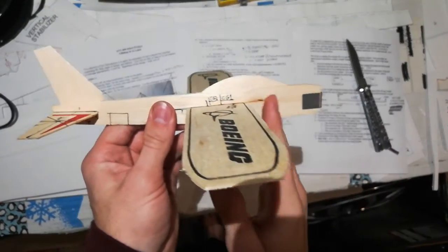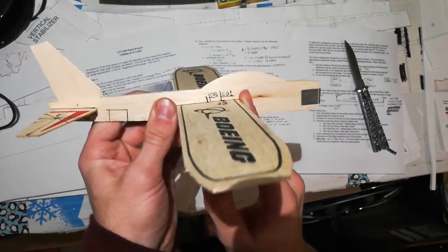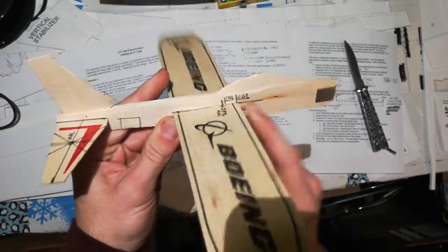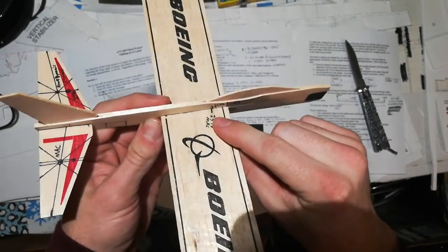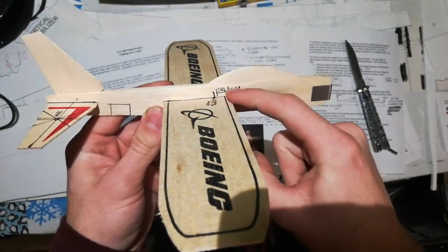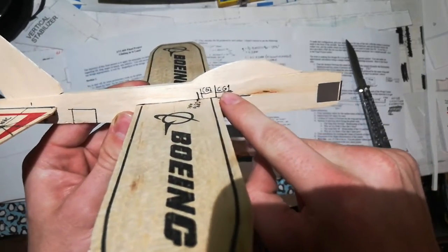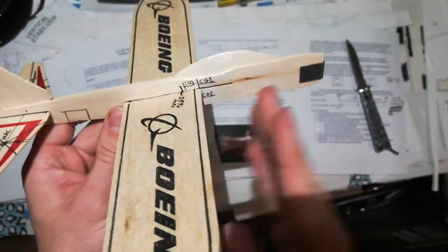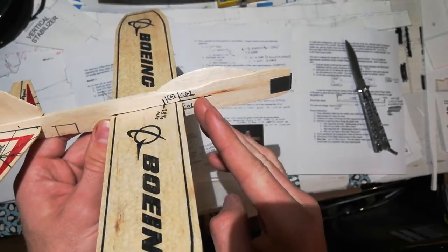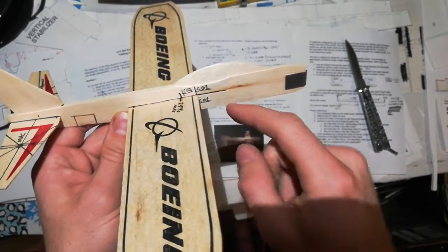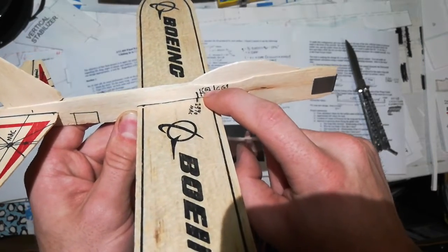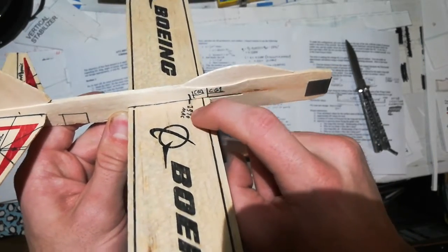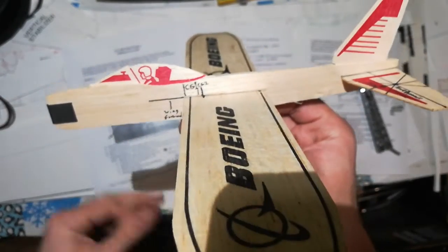Now, by sliding the wing to the rear, you can see it actually moves the center of pressure back behind the center of gravity. So here we have CG1 marked as the center of gravity when the wing is in the forward position. And of course, moving the wing back moves the center of gravity back due to the weight of the wing. But now you can see the center of gravity is slightly forward of the aerodynamic center point where the center of pressure is.